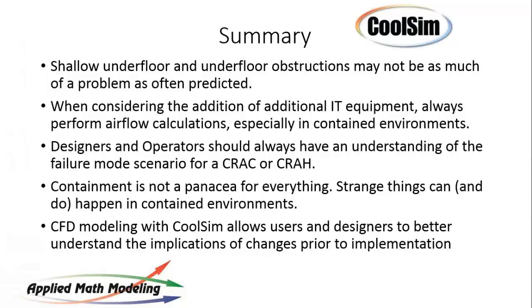The other point here is that when you think about adding extra IT equipment, always think about the airflow required. I hear a lot of users out there, Lauren, talking about, well, I've got so many tons of cooling, therefore I'm safe. Well, you have to have the cooling in the right place. Yeah, you've got to have the air in the right place, both the supply and the return. It's not just about cooling capacity. It's about how much air is being delivered, and that's often the limiting factor.